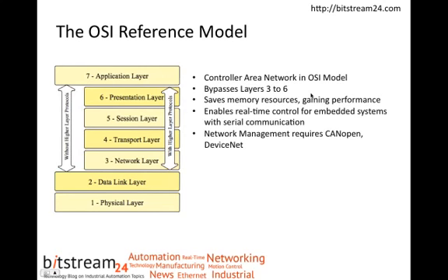In stark contrast, a CAN implementation is far simpler than industrial Ethernet, meaning that despite its technological shortcomings, it is very easy and inexpensive to implement. The standard CAN implementation bypasses the connection between the data link layer and the application layer in order to save on valuable memory resources by minimizing the overhead and as a result gaining performance as needed for embedded solutions with limited resources.